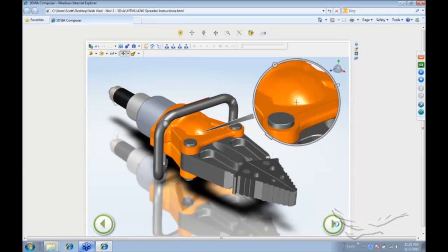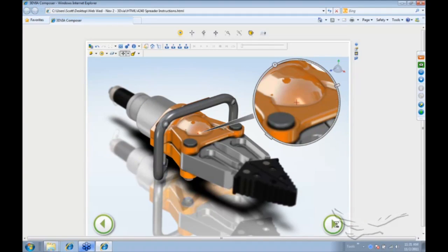And there we go. This is like the marketing image here. We'll take a second to create all the rendering styles. This one's really cool. We've got the depth of field, we've got the digger tool associated in there, and just a real high quality marketing image. And you can see that this view here doesn't have the lines visible. That's because this view is specifying that no lines are visible, where the other views are referencing the neutral properties, and the template chooses what that neutral property is. So that's the reason behind that.